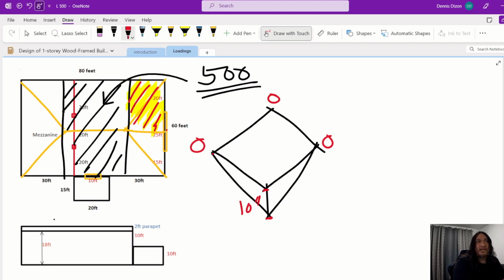This is the same calculation as in surveying, cut and fill, where you calculate the volume of your cut or fill. You have four corners, get the average, and multiply by the area, that is your volume.